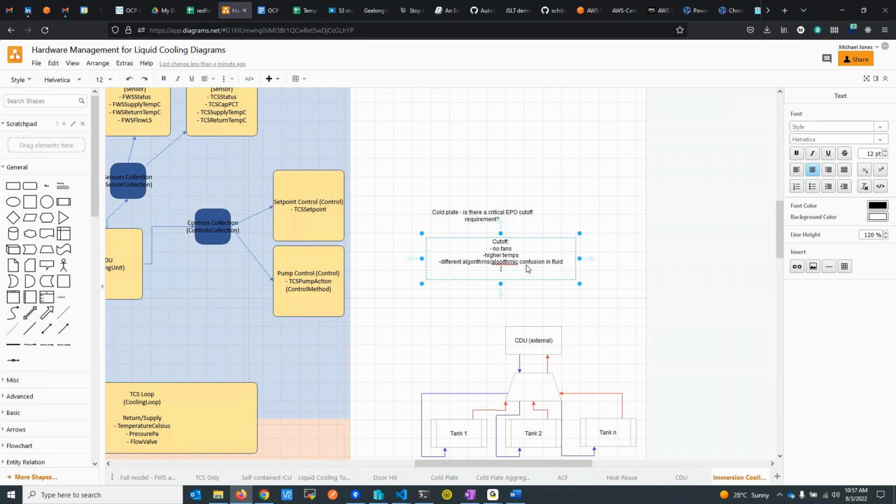It's just a question then. Are we controlling the whole PDU? So will you shut down the whole PDU for the whole service, or will you have a control per outlet? I would say it would be recommended to have a per outlet control, to be able to discriminate which server is going to be shut down, or a group of outlets if this is redundant. Yeah, because there's no point shutting down all the servers if there's a problem with one server.